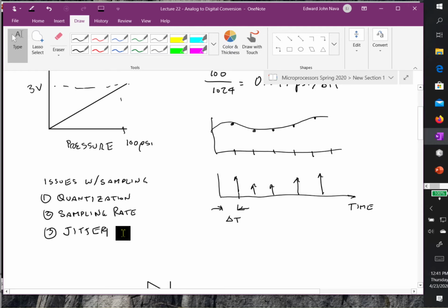One of the reasons I'm getting a few comments is about the wheels appearing backwards. I didn't mention that when a camera is taking a video picture, it's taking samples, or taking pictures, at an interval, maybe 30 times a second. Your TV's rastering at 60 times a second. So I'm not sampling at a fast enough rate to capture either the rotating wheels or rotating propeller, and that's why you have this problem called aliasing that distorts the frequencies and they look like they're incorrect.